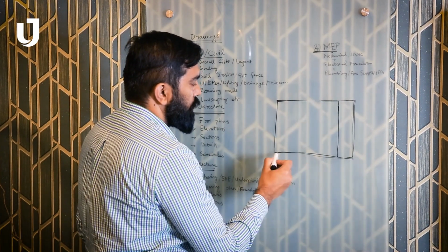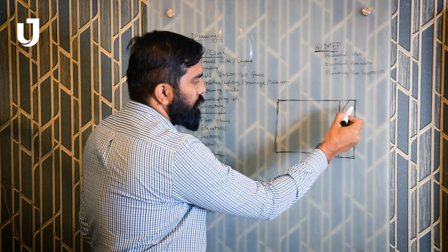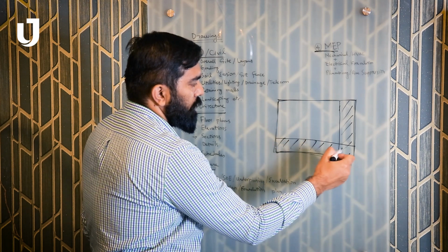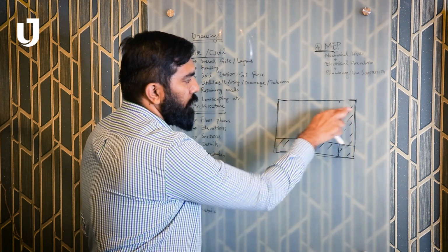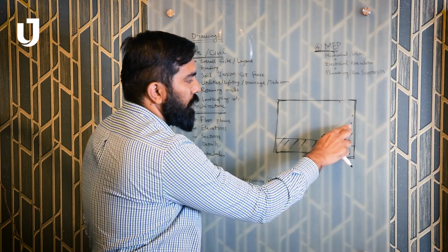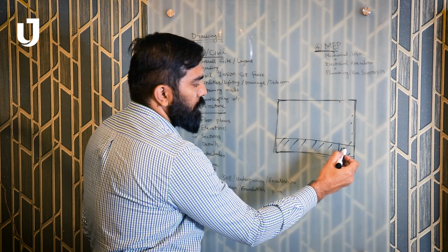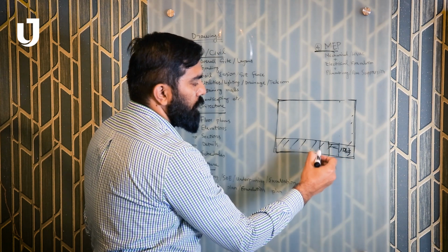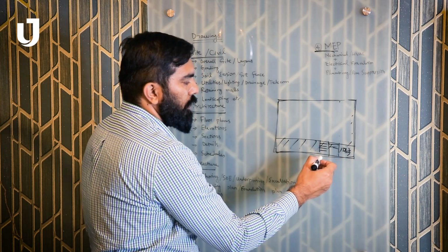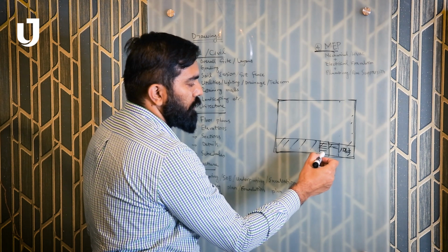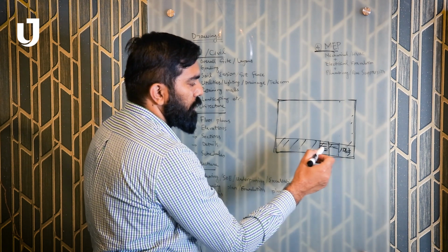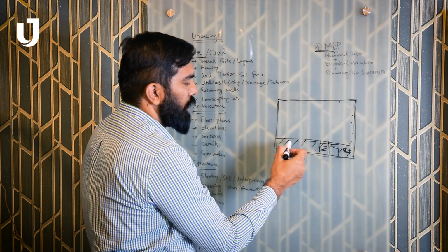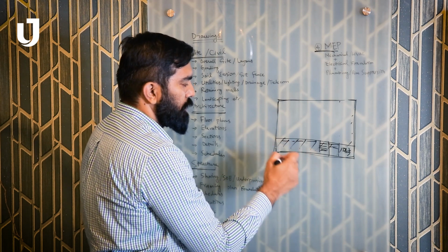And here is the typical sheet of the drawing. In this sheet, we have a seal over here, or you can have a seal over here, like this. In the seal portion, we can have the drawing number, the drawing title, maybe like here, and in this portion we can have the revisions. That's going to tell us what is the latest revision date of that particular drawing page. Here you can have the particulars of the architect, the project, the client, or other consultants if they are in the project.